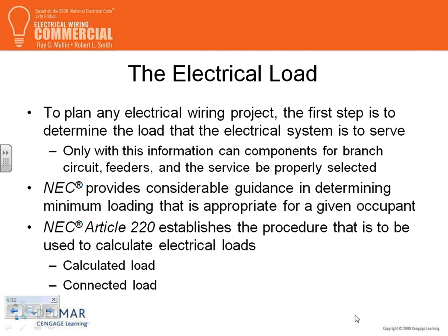The other chunk, if you guys remember, is volt-ampere for receptacles. Every single receptacle in the building, we're going to assume has 180 volt amp. So, piece of cake, multiply them all by 180, add them all up, and then derate them. The first 10,000 at 100%, anything higher than 10,000 at what? Anybody remember when we did the load calc? The first 10 at 100%, anything higher than 10, cut it by half, 50%.